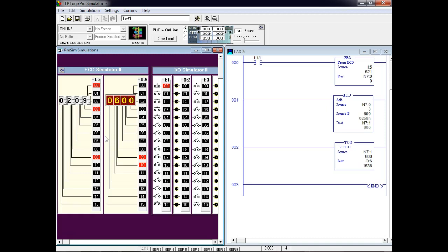If it was hexadecimal, it would go from 0 to F, right? So notice the biggest number I can put is what? 9. Okay. The smallest number I can come up and put is what? 0. And this is showing you exactly what it's giving me. So it's giving me BCD, right? You understand that? This output right here, I think this guy will do hex. You'll very seldom see that, but I don't want it to do that. So what I'm doing is I'm sending it a BCD code and then it's displaying these numbers for me.